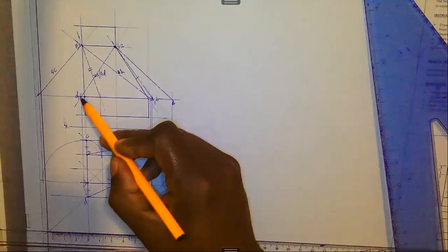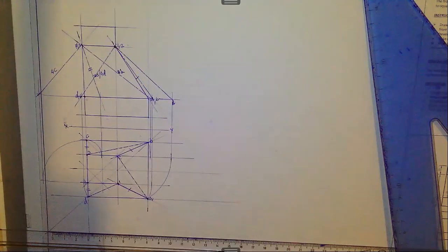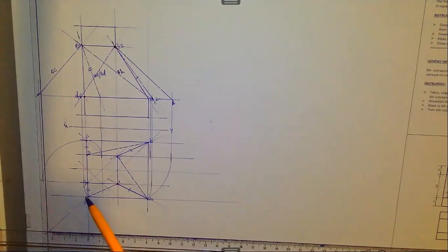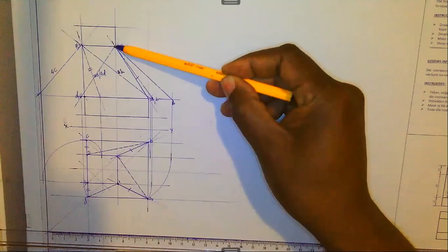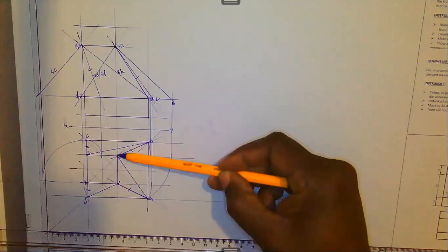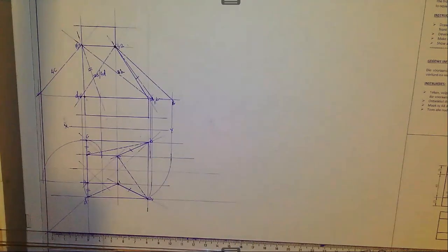There are certain things that are not going to change here. If you check D to A, they are both parallel to the ground line, so they are true lengths. If you check 1 to 2, it's seen as a point here, so automatically this is a true length. So those concepts that we did in grade 10 with regards to descriptive geometry now come in handy in terms of our work. Now I said there are 2 methods that we can use. For the sake of time, in our next task, I'm going to use a different method in order to illustrate the establishment of the true length.